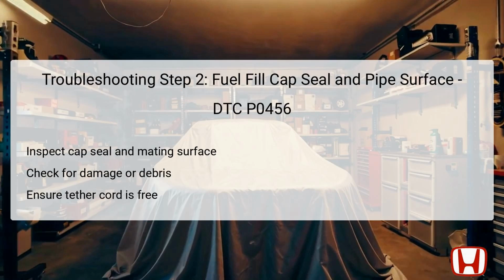Next, a visual check of the fuel fill cap seal A and the fuel fill pipe mating surface B is essential. The seal must be intact without cracks or deterioration, and the mating surface should be clean and free of debris or damage. The tether cord C should not be caught under the cap, as it can interfere with sealing.